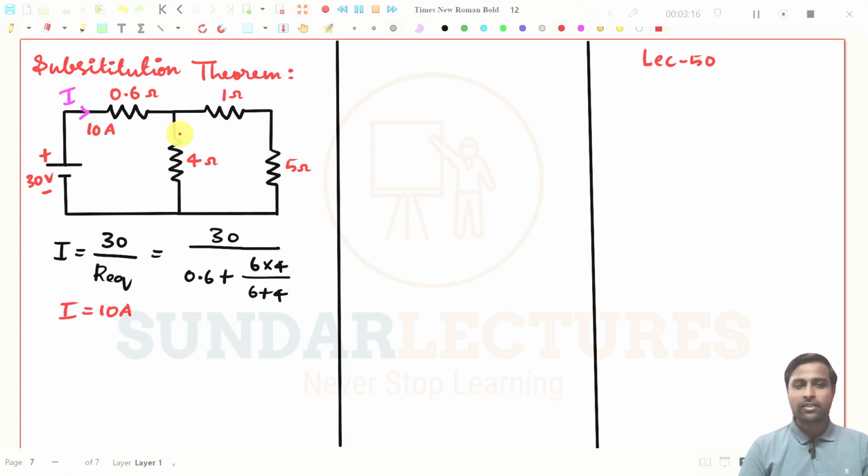And if I want to find the current here, in this direction, I need to find the current value in this 4 ohms resistor. Here the 6 ohms resistance and 4 ohms resistance are connected in parallel. So apply the current division rule. I will put this as I1 and this as I2.